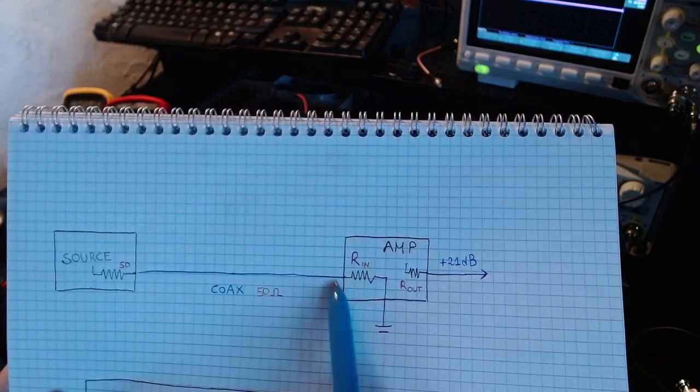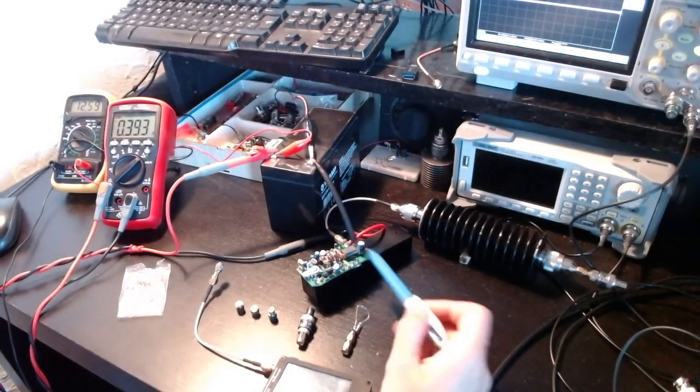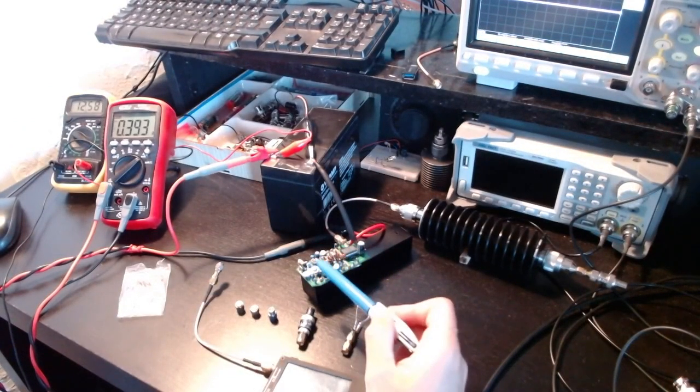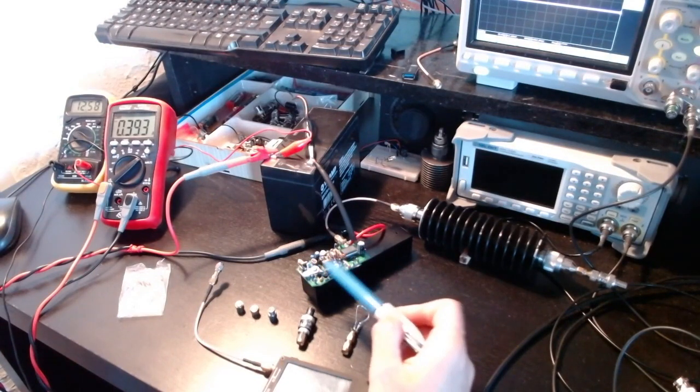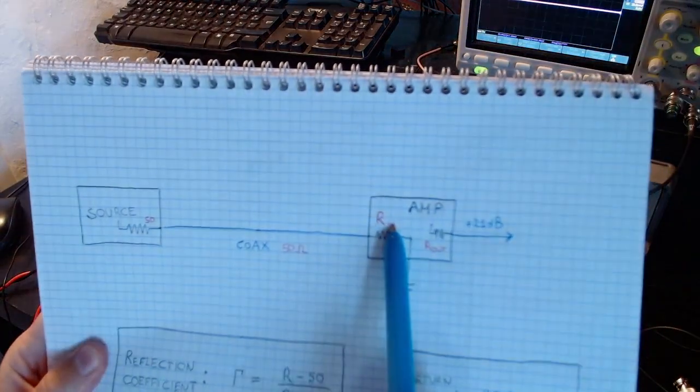Because in the datasheet of this amplifier it is basically unspecified. So it says that it can vary. It's not 50 ohm, okay? So you should not expect this amplifier to have a 50 ohm impedance, so this is unlikely to be 50 ohm.